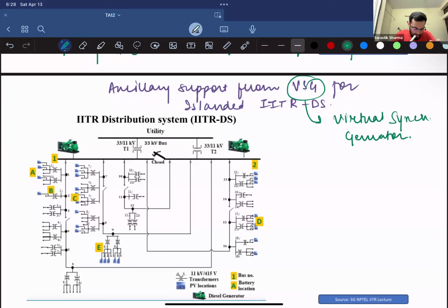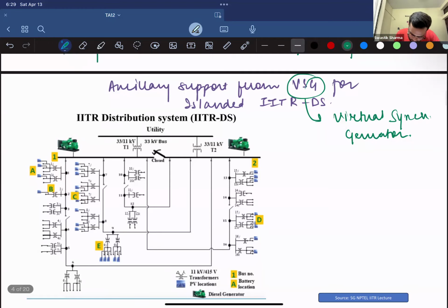these highly intermittent resources, and your BESS and other equipment, the inertia of the system goes down by a very high margin. Now, this inertia, you all know, is very important to make sure that your frequency doesn't dip. If something happens, if there's too much loss of generation, the frequency starts dipping. So when this generation loss happens, the frequency dips. So I'll just show.